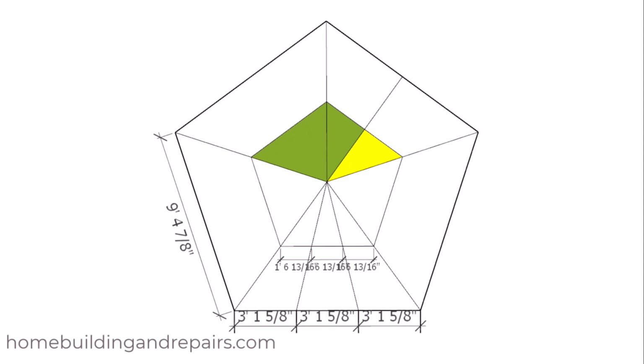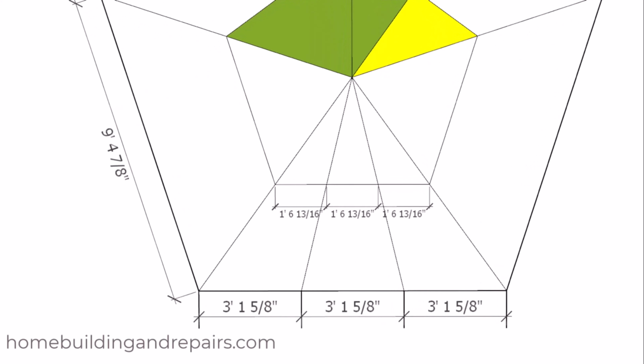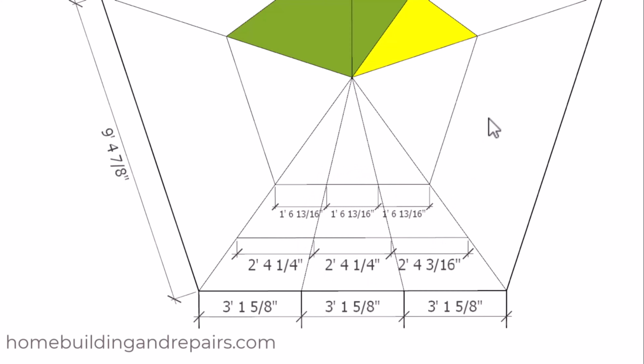And as always, whenever you're building stairs, you've got to double check all of your measurements. So again, the angles here are going to be different, and you're not really going to be worrying about the angles. You're going to worry about the measurements, including the walk line measurement should be exactly the same in each section. So for example, I could use the measurements here for this section and this section also.